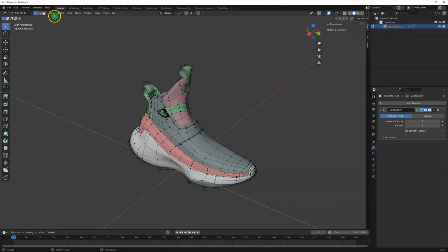But now if we go Select and where is it? I just press P on the keyboard because I know what the control is. So we can separate our model by selection. We can separate it by material. So if we apply the right color materials to our parts, then we can separate them and keep those like colors connected. And when we put a material onto one of them, it'll apply to all of them.